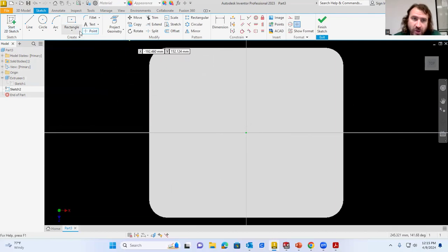If I go to my point tool, click on it to activate it, and go to this fillet edge, and put my mouse there for a moment, it's going to highlight it. More than that, it gives me this black dot right there. I went on top of it with my green dot, and that is the center point of that fillet. So I can click on that, and now this dot is centered on the center point of the fillet. I can go over here and do the same thing, and down this one, and the same thing. Again, I can get pretty quick at it.